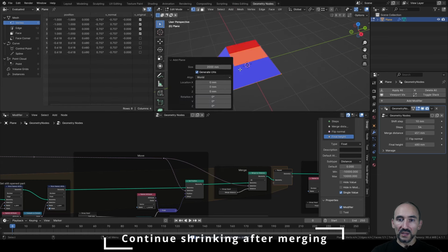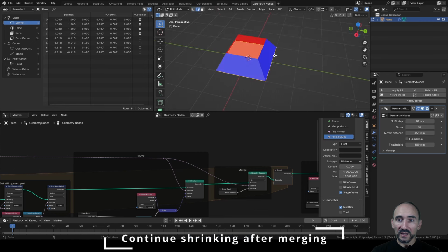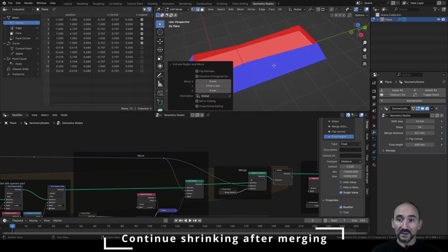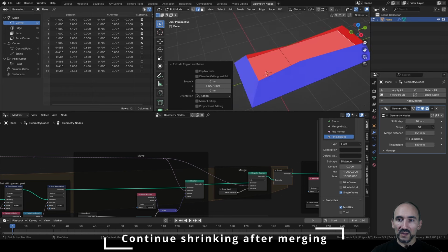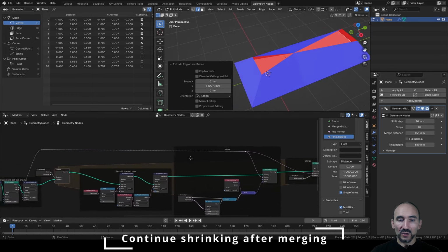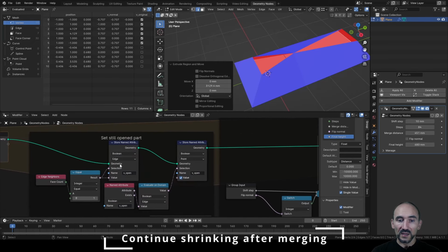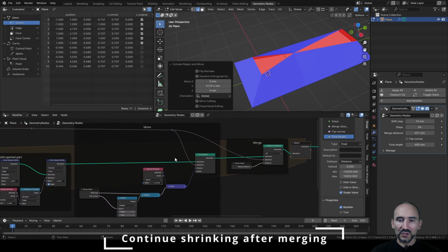I'm going to create a new plane, and I will select this edge and extrude it a little bit like this. And as you can see, if I increase the step, I have merged vertices here, because for each step the system will recalculate the still open edges like these three and these three, and continue to set the new position also if I increase this step like this.